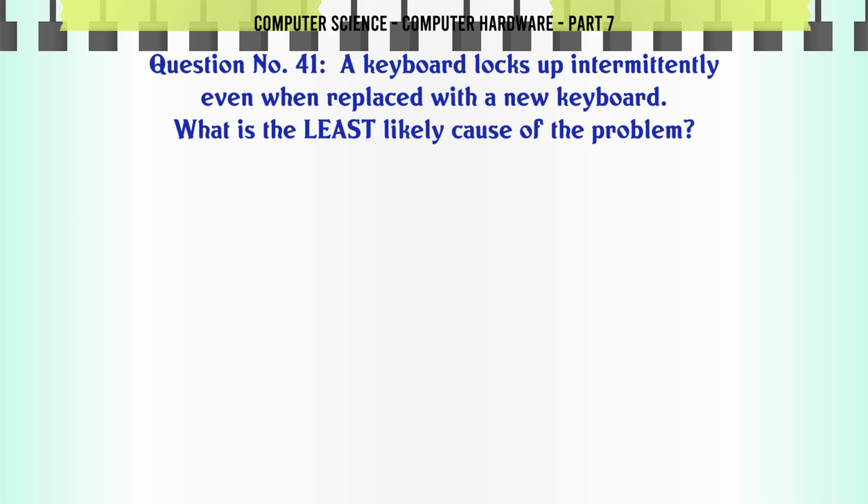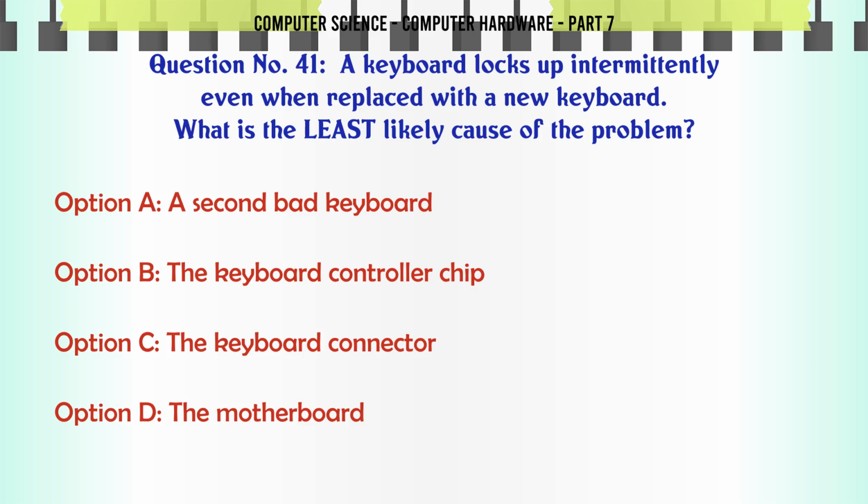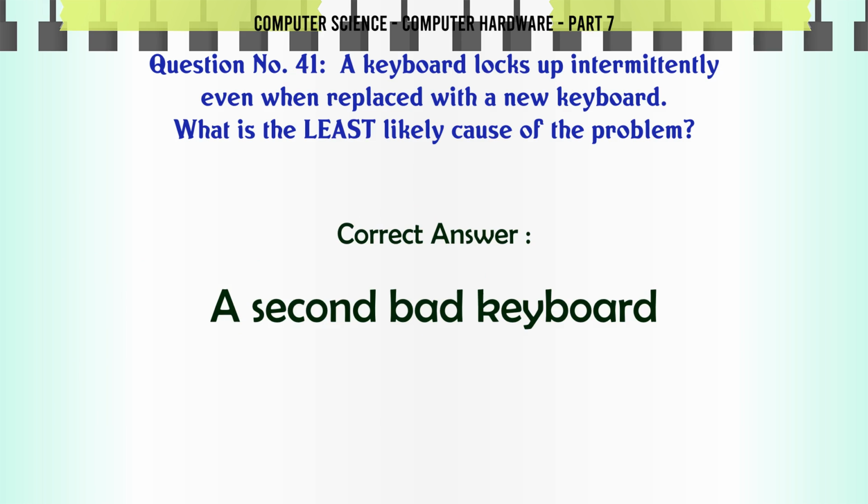A keyboard locks up intermittently even when replaced with a new keyboard. What is the least likely cause of the problem? A. A second bad keyboard, B. the keyboard controller chip, C. the keyboard connector, D. the motherboard. The correct answer is a second bad keyboard.